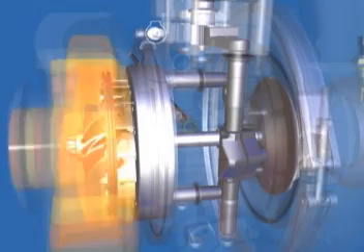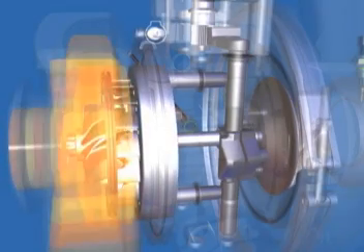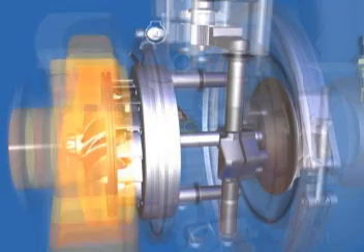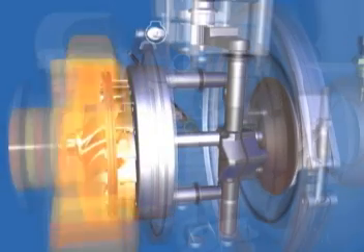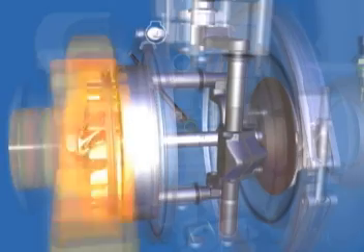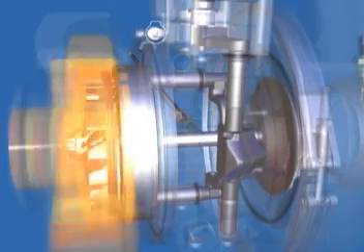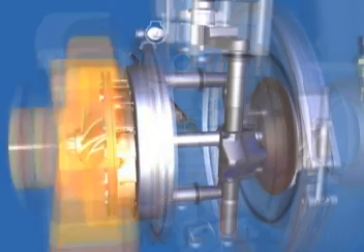The sliding nozzle inside of the turbine housing adjusts to vary the turbine volute exit area. This action creates the increased back pressure in the exhaust manifold to force some of the exhaust gas through the EGR valve when it opens. The sliding nozzle is adjusted by the VG actuator.